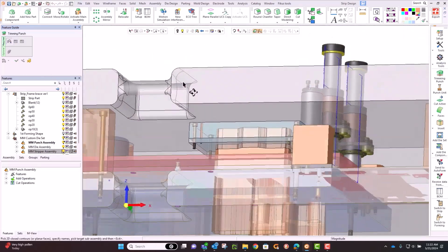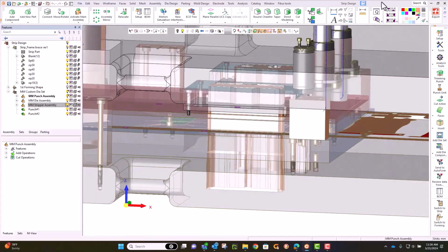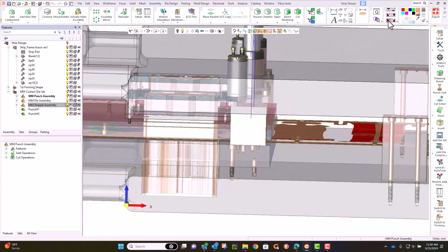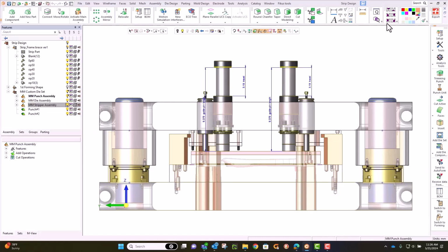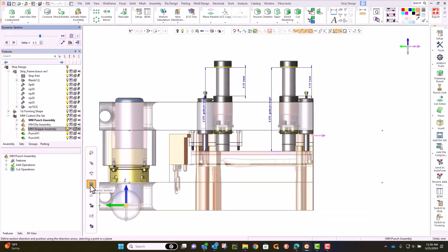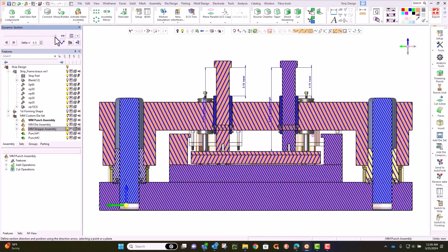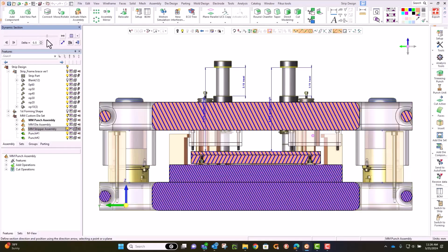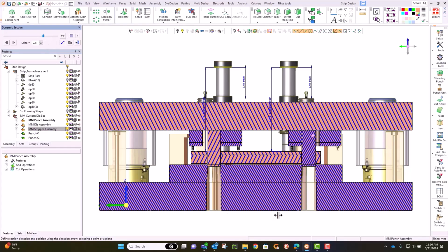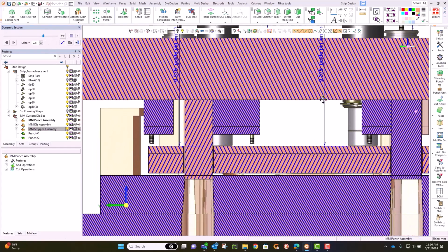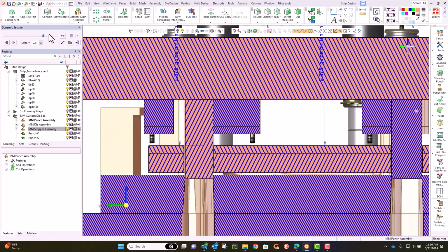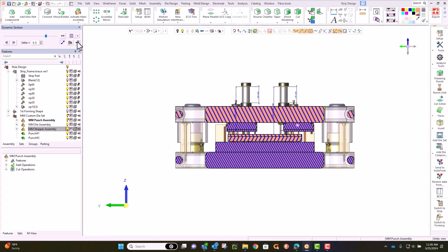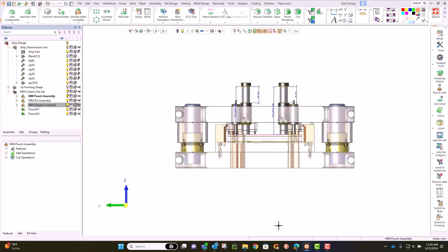So I've got the land, the die life in the die steel, and then it tapers open 1 degree, 2 degrees, whatever I put in my setup, and then it opens up wide to drop out through the bottom of the shoe. So all my clearances are established and set, and now every punch I pull that way, I know I'm going to have the right configuration, the standard configuration that my shop uses day in and day out.